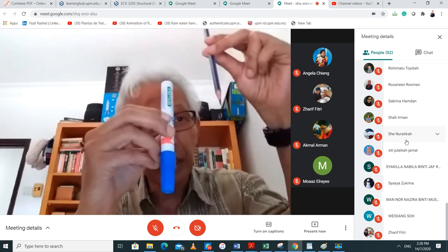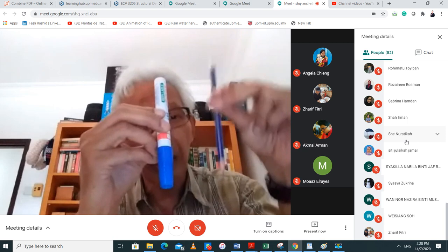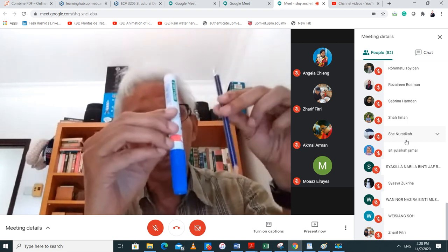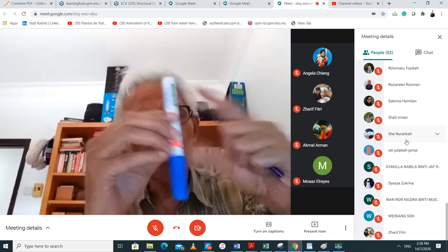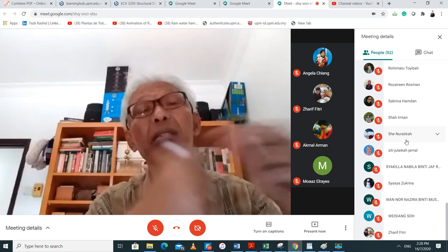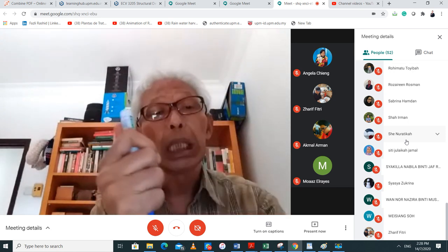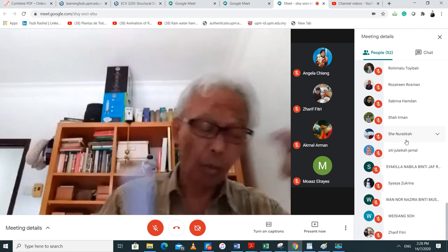At every depth, I take the tip resistance Q sub C. So if my pile is here, I can have all these Q sub C. I average them, I divide by 200, and I say that's the shaft friction for the pile, multiplied by the area.